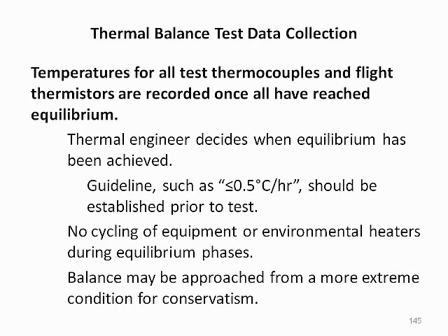For conservatism, thermal balance may be approached from a more extreme condition. For example, one can cool a spacecraft to below the expected thermal balance temperature and then allow it to warm to thermal balance. If steady state is declared too early, the measured temperatures will be a little on the low side, which would be conservative for a cold case test.